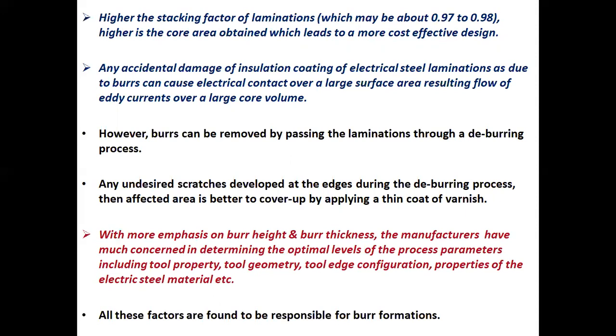Any accidental damage of insulation coating of electrical steel laminations due to burrs can cause electrical contact over a large surface area, resulting in flow of eddy currents over a large core volume. However, burrs can be removed by passing the laminations through a deburring process. Any undesired scratches developed at the edges during the deburring process, the affected area is better covered up by applying a thin coat of varnish.